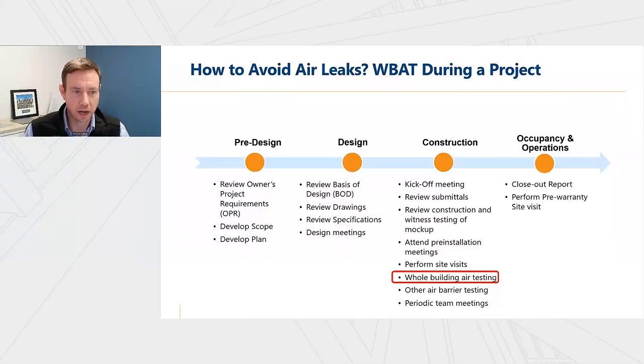Hopefully all these other quality assurance and control items occurred before whole building air leakage testing. And then once the enclosure is complete, there's usually a pre-warranty site visit and closeout report. The benefit with working with an enclosure consultant or commissioning agent is that an enclosure consultant can not only perform and observe testing, but can provide this continuity of all these services throughout an entire project.